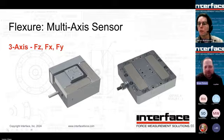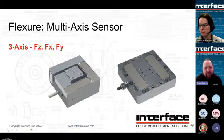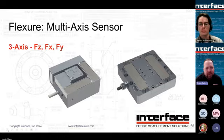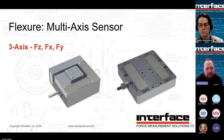So, multi-axis and flexure consideration. Here are two different options to accomplish the same thing in terms of offering a sensor that will do FZ and XY shear. The one on the left, you can imagine, was one big spiral. Those are essentially 3 bending beam sensors bolted together. You can see the little gauge potting that covers where the gauges are, with the white areas. So you can imagine that they all kind of tie together.